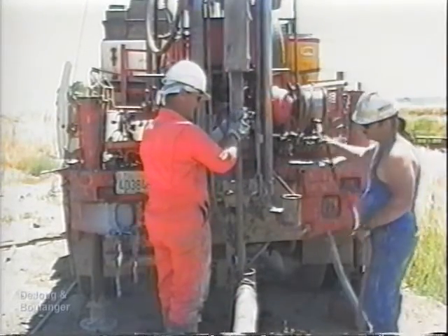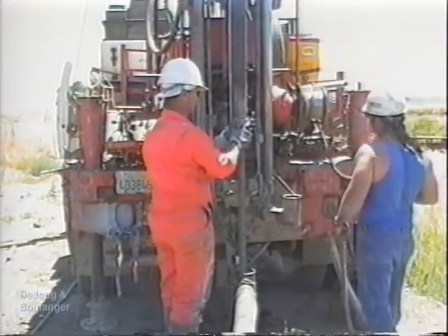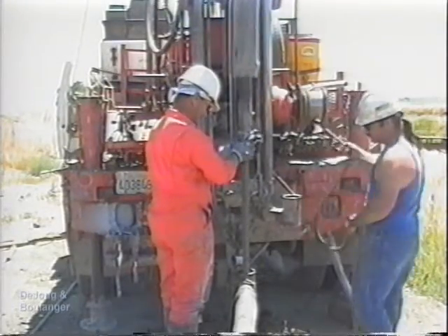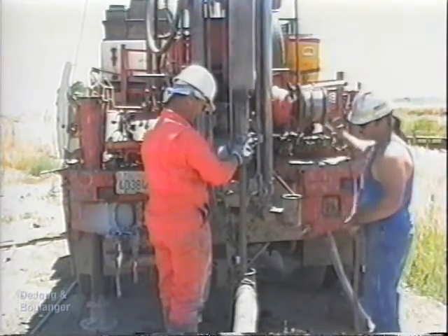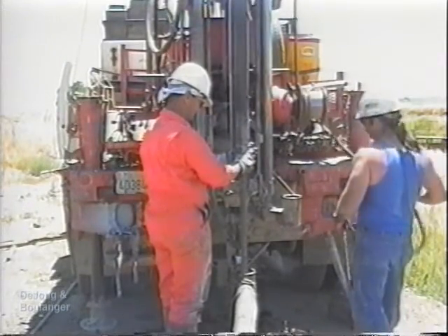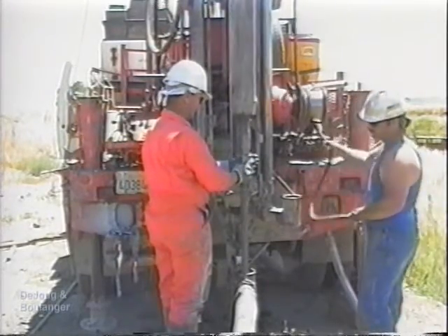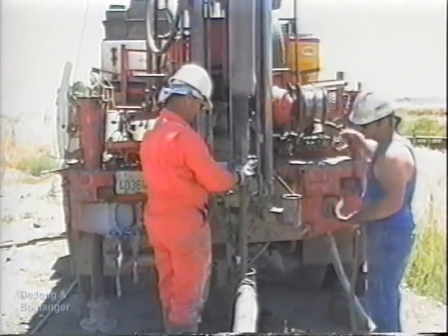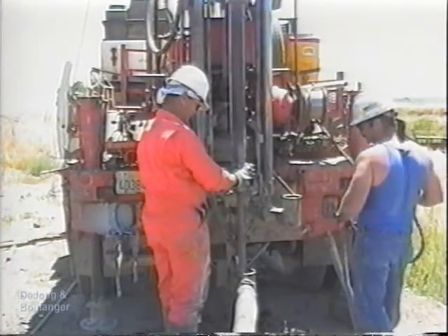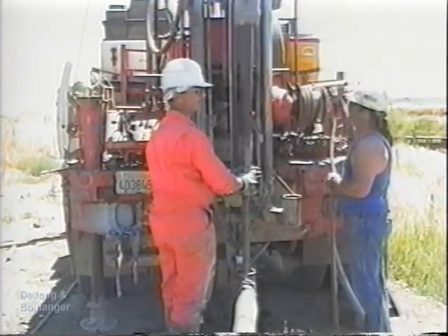Generally, the better the quality of the sample, the more expensive and time-consuming its recovery is likely to be. For some purposes, such as designing the foundation of a light structure on stiff clay, the expense of obtaining high-quality samples may not be justified. On the other hand, when the compressibility or shearing strength of soft clay is needed to evaluate the settlement or stability of a critical embankment or structure, even the best samples may barely be adequate. Consequently, there is a need to establish a quantitative measure of the quality of samples, especially for soft clays and silts.